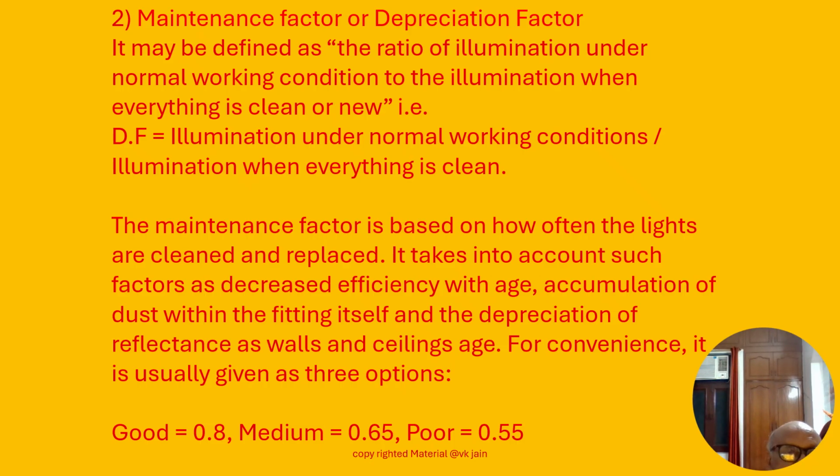the next factor is maintenance factor or depreciation factor. It may be defined as the ratio of illumination under the normal working condition to the illumination when everything is clean or new. That is, depreciation factor is equal to illumination under normal working conditions divided by illumination when everything is clean. The maintenance factor is based on how often the lights are cleaned and replaced.